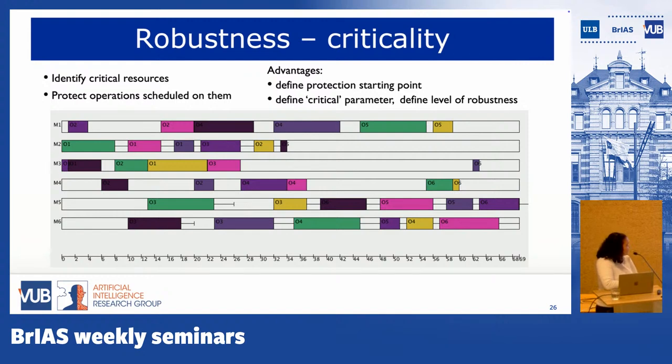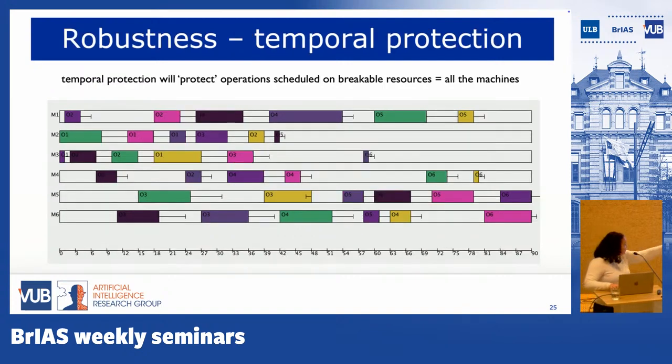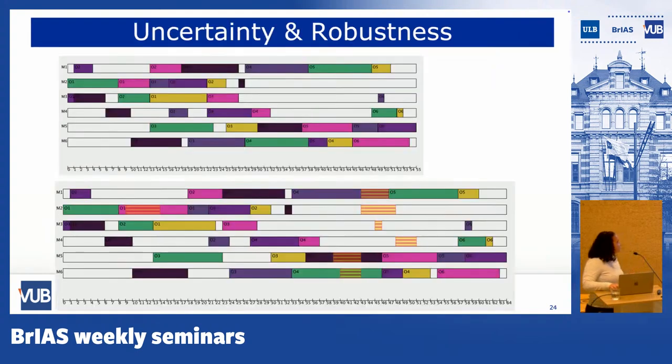but of course, this can also be learned after executing several experiments. If we use this idea, then here we define that the machine is critical if it has 4 operations or more in a consecutive way. And then we were extending the processing time by 10%. And then here, we will be telling the user we need 69 days instead of 90 as the original method. And that's a bit more realistic compared to the 55, which is the optimal solution.